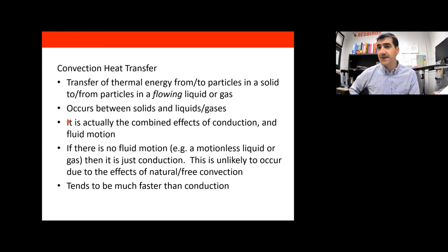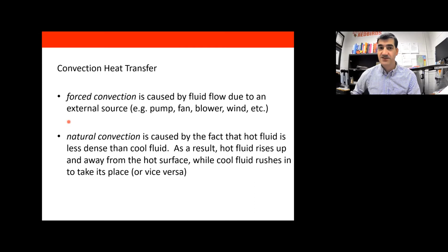Okay, so it's really the combined effects, which is why it's a little bit more complicated. It's really the combination of conduction of heat flowing from the solid to the fluid, and then the motion of that fluid. The motion of the fluid is carrying that heat away. Of course, if there is no fluid motion, it's just conduction, like I said, and this mode of heat transfer tends to be a lot faster than conduction. Previously, a week ago, we defined these two terms. There's a term called forced convection, which is caused by a forced fluid flow.